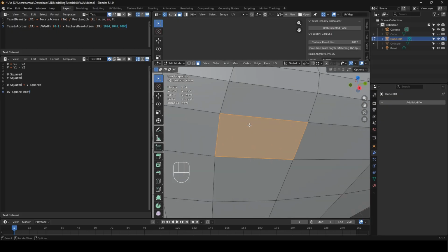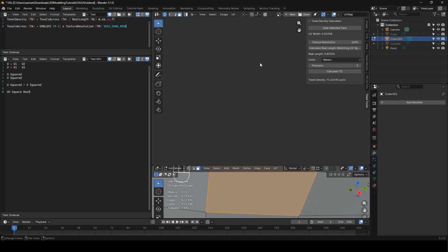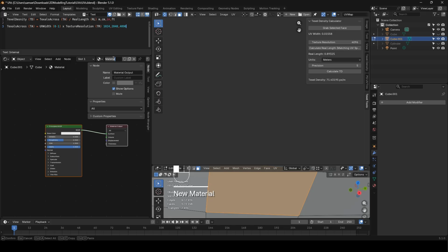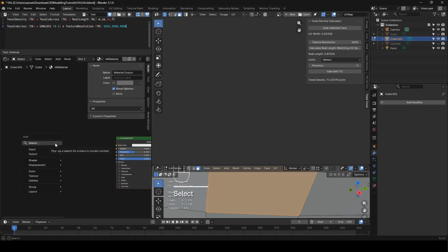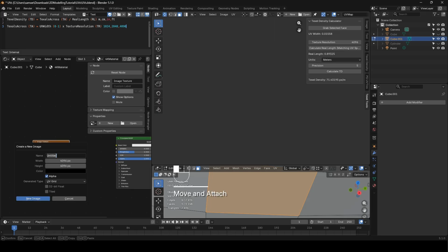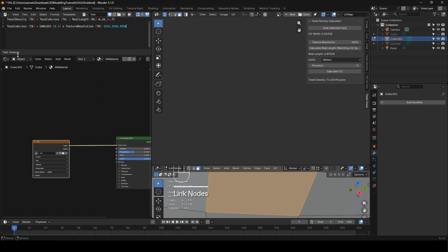So now that we've got this, we're going to zero in on it, and then scroll down, and then what we'll do is we will give it a shader, and then we'll make a 4K material. So we've been dealing with 2048, we've dealt with 1024, so let's do a 4K texture. So image, texture, new, and then we'll just call this 4K, make it a UV grid 4096, and then just hide that, and then plug that in.